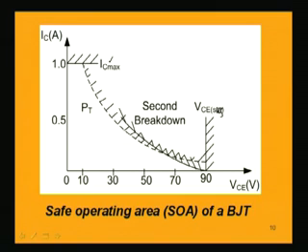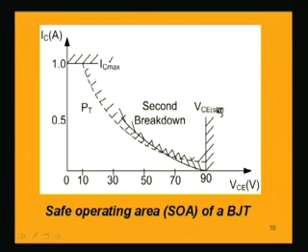And the power dissipation in the transistor is given by this curve, because we know that power dissipation in a transistor is basically the collector current IC times VCE, that is the collector to emitter voltage. So when VCE is smaller, the collector current will be higher, that is very obvious from the output characteristic of the transistor.